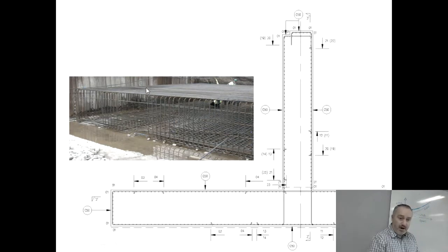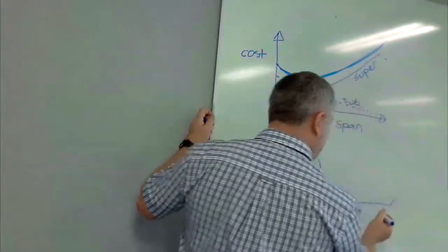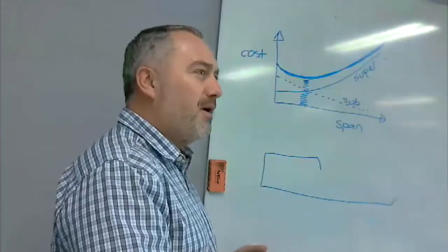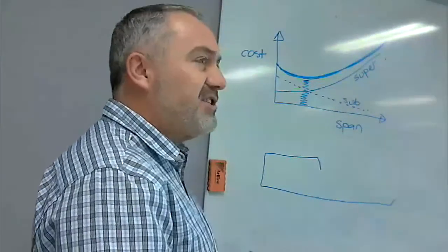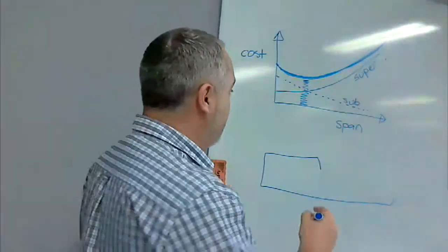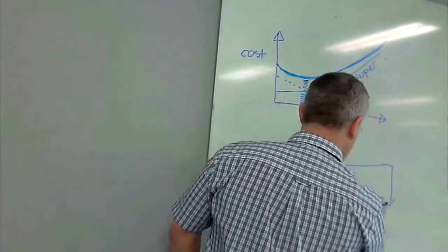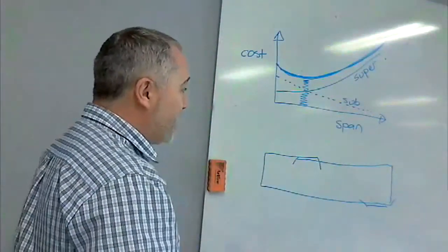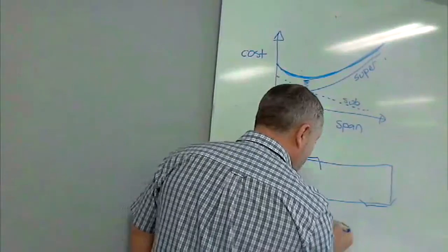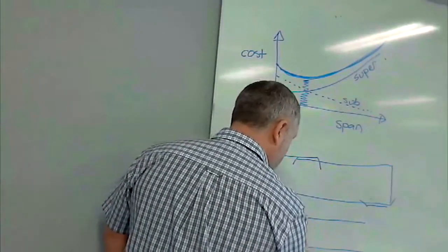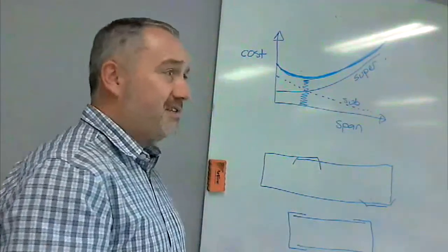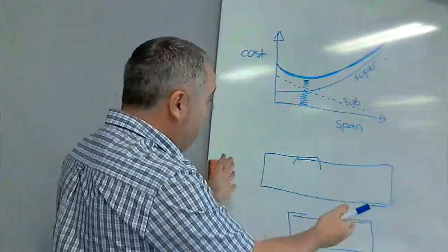Like these bars here, starting at number 4 and then going all the way along to about here. Does anyone know what they're called? Some people call them trombone bars. And civil engineers apparently specify them all the time. And you put another one in, like that, to close everything up. Whereas steel fixers prefer bars on the top and then two sort of C shapes, just because they're easier to fix, and it doesn't really matter which you do.